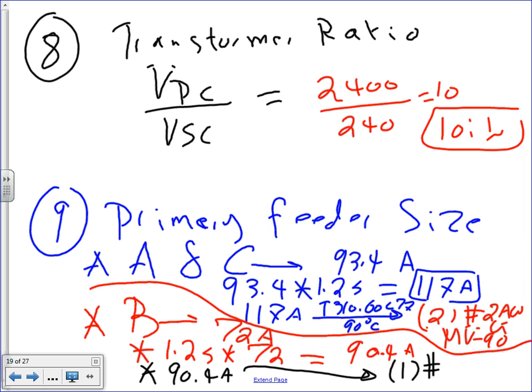Same table. Number 4 AWG, MV-90 degree. One conductor. So, Jamie, can you see that two of them are going to be number 2 and one's going to be number 4. So when you look at the transformer, guys, you're going to see literally two of them bigger, thicker than the third one. And that's okay. Not a big deal.